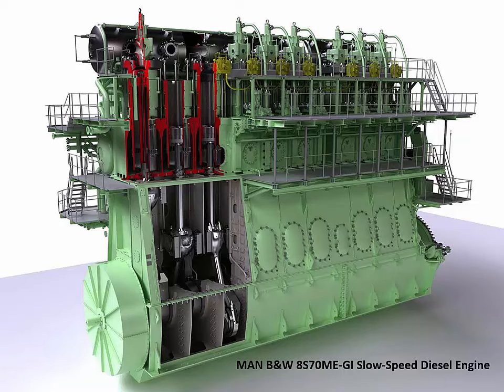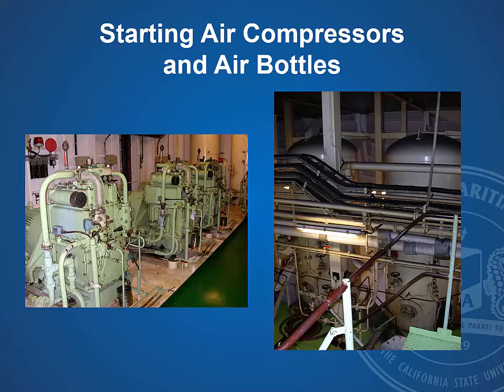It's best just to drain your start air receivers or make absolutely sure that the line that you're working on is drained prior to any work commencing. You'll typically have between 2 to 4 main start air compressors. The ones that I've typically seen are piston type, though I believe there are now some rotary high pressure air compressors out there. The simulator uses these piston type, and that is what we're going to discuss today.